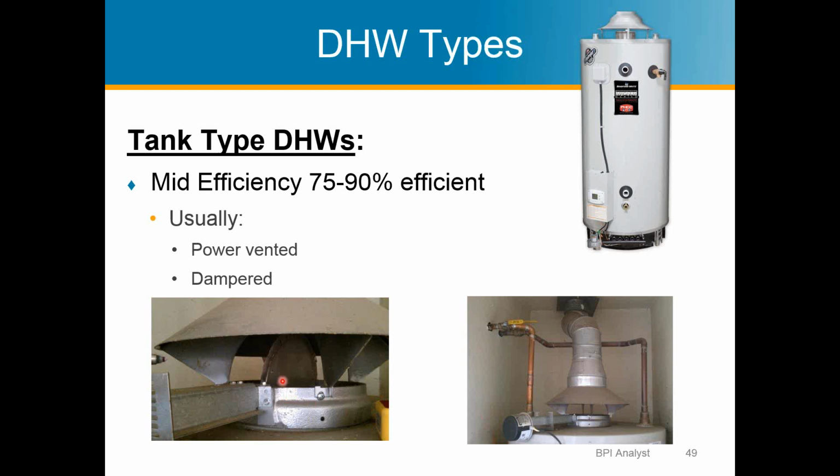So here, when the damper's open like this, it should be firing, so it's heating the water. When it's off and you're no longer firing, the damper closes, and it just helps seal in the air, so it stays more efficient. The burners are down here, and typically these are going to be electric ignition, where most residential water heaters have a standing pilot. A standing pilot just typically is going to be wasting energy.